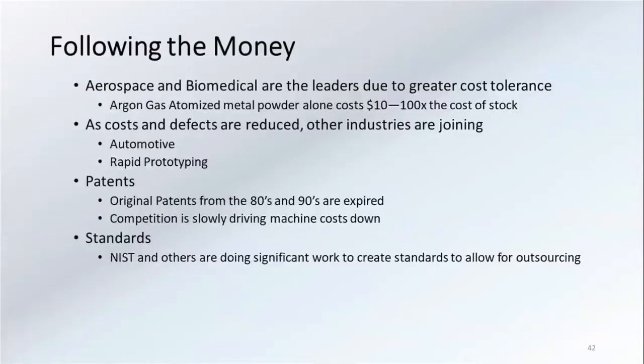So this comes back to the following the money question, where laser powder bed fusion usually costs 10 to 100 times. The metal powder alone is a lot more costly. If you need the complexity, if you're doing something that is low volume, or you just need several rapid prototypes out the door quickly, those are great. This is a great option for you. There is money to be made here, but you have to just realize that it's more expensive than CNCing it.